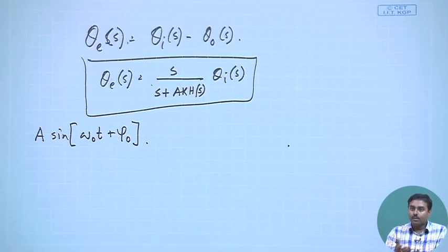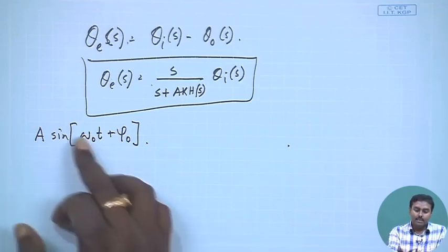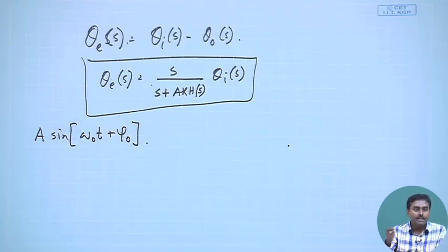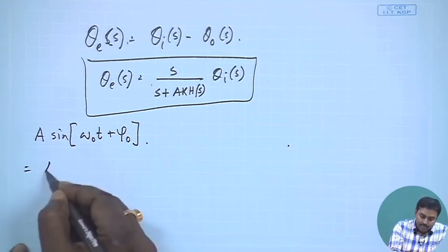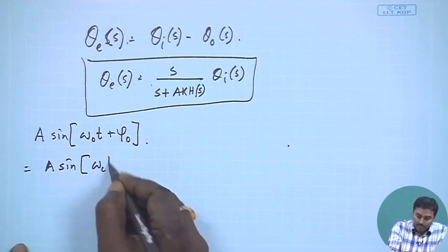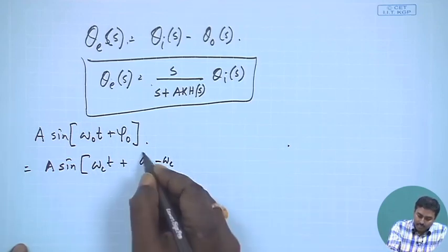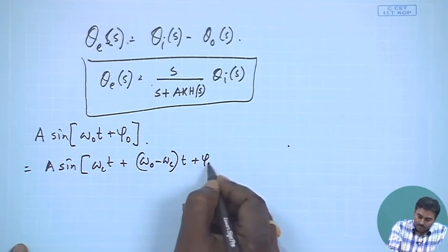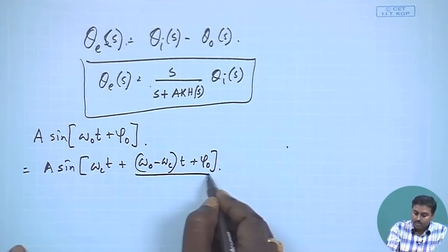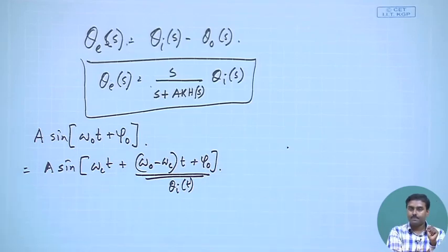So, whatever it is, we will be getting that. Now, the VCO generates at omega c. Okay. So, immediately I have to calculate the effective theta i(t) with respect to that omega c. So, I can write this as usual, or as the previous case, as omega c t plus (omega 0 minus omega c) t plus phi 0, right. So, that becomes my theta i(t), right.